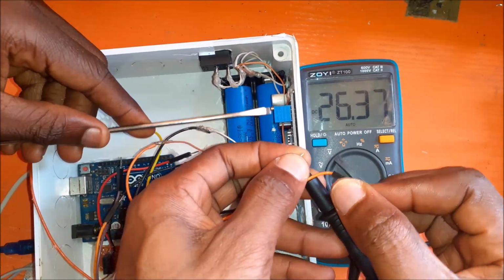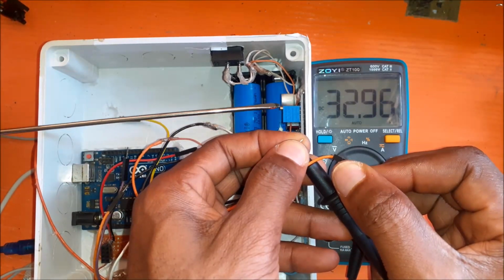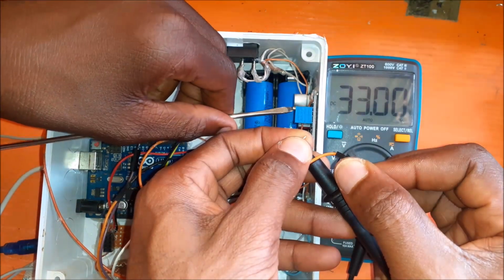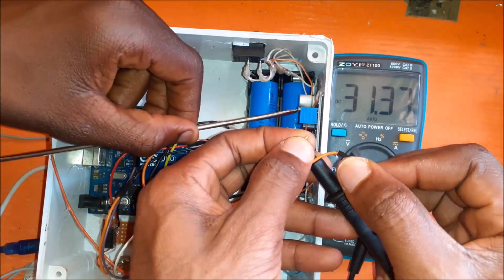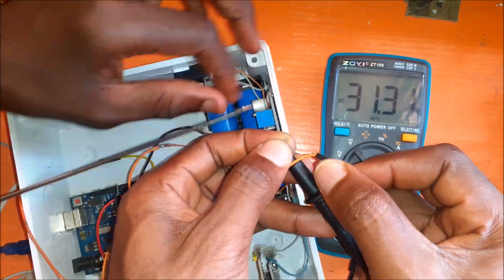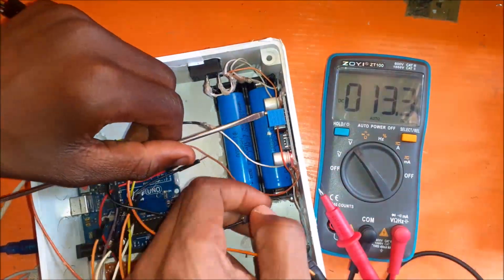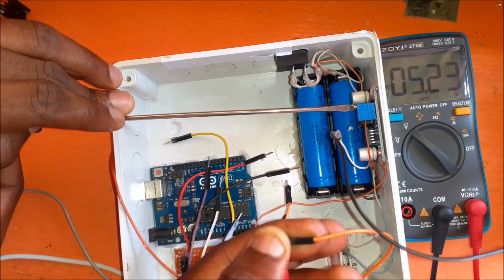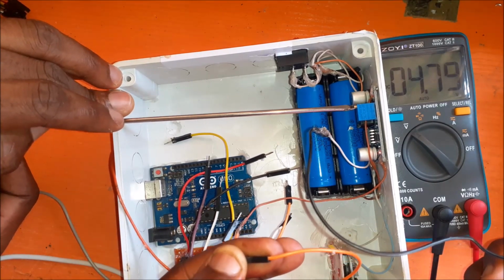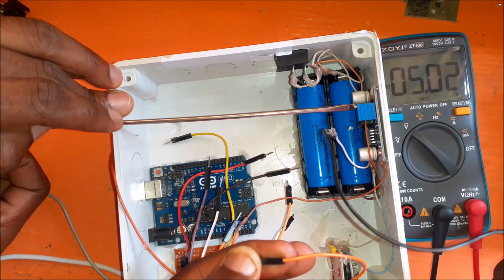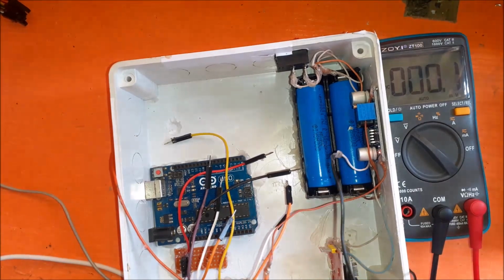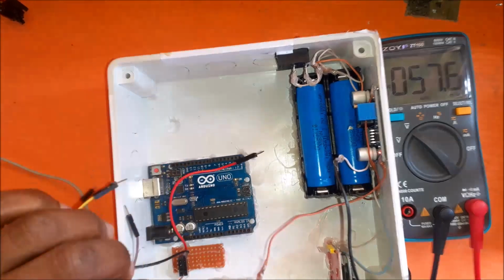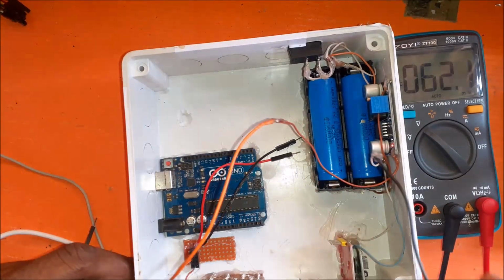Since this is the logic level all of them are using, except for the ECG sensor module whose comparator board uses a logic voltage of 3.3 volts, we can source the 3.3 volts level from the Arduino Uno board, since it has an onboard regulator that can give us this output. We made a multiple output channel for this 5 volts logic using female header pins soldered onto the Vero board, where the modules and development board can be connected to get the 5 volts logic levels.